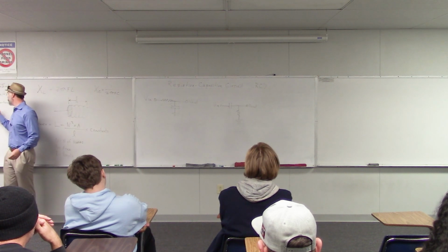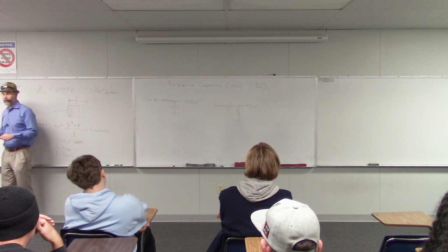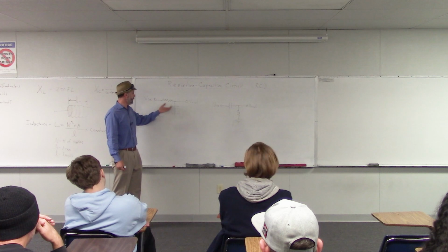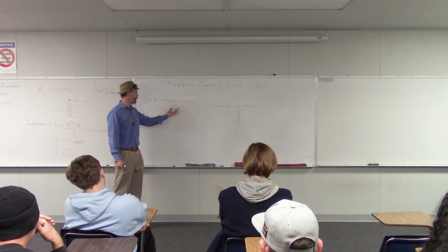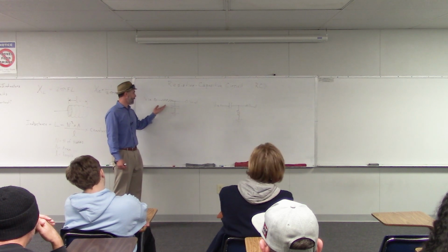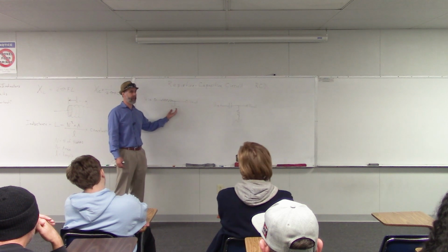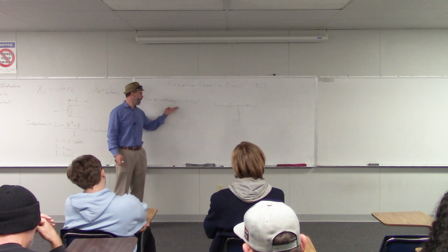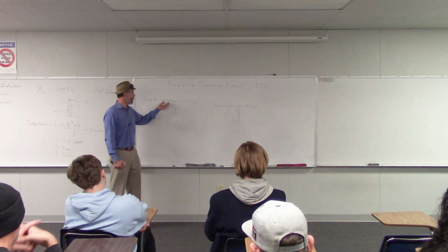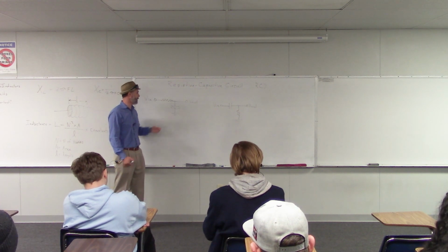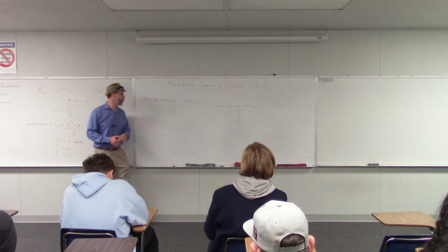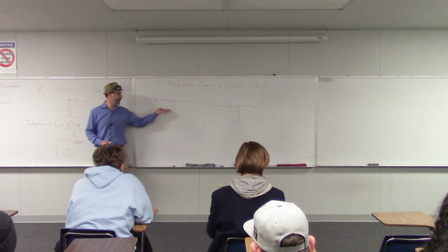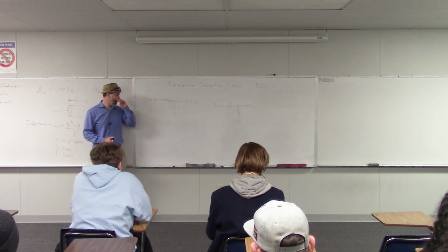So that's the basic principle of how these circuits work. If you choose a big resistor and a big capacitor, that's going to take a long time to fill up, so it would have a long charge time. Whereas if you chose a small resistor and a small capacitor, that would fill up quickly, and you'd have a short charge time. So that's the way that you can affect the charge time.